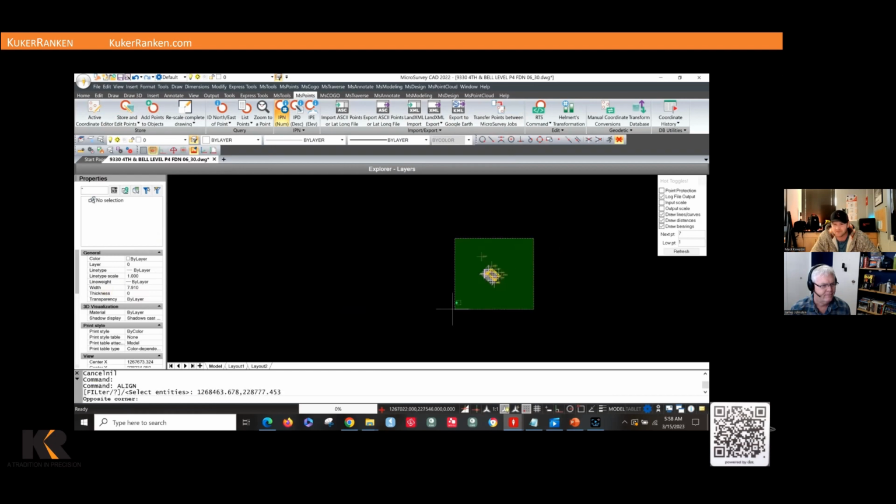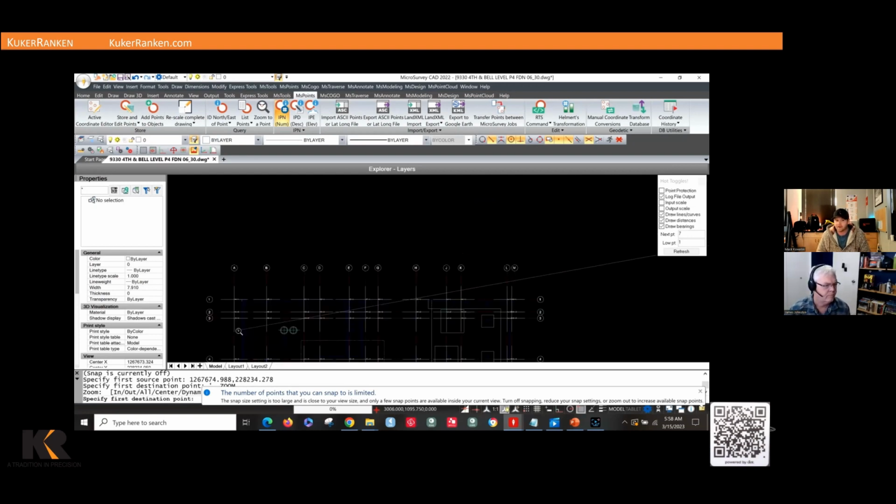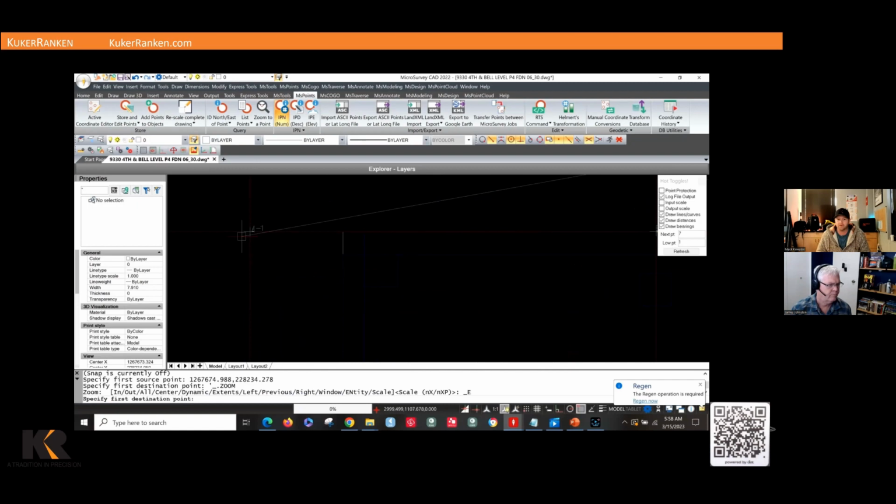So I'm going to select the first point, and I know that this point here, because I'm looking at the ASCII file as I go, is A and 1. So I'm going to go ahead, turn off the grid snapping, grab my node, run on over to my user coordinate system, which we can now easily see as we zoom out. I'm double clicking on the center mouse key right now. And as you can see, those point symbols are 5% of the screen, no matter how big or small that screen gets.